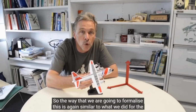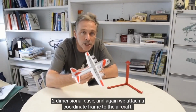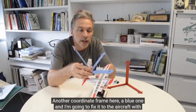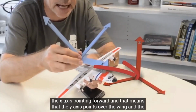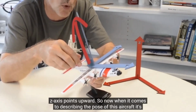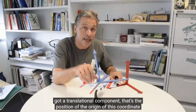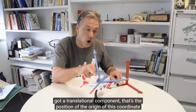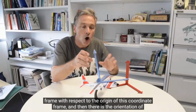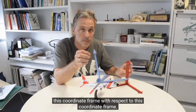So the way that we're going to formalize this is, again, similar to what we did for the 2-dimensional case, and we're going to attach a coordinate frame to the aircraft. Another coordinate frame here, a blue one, and I'm going to affix it to the aircraft with the x-axis pointing forward, and that means that the y-axis points over the wing and the z-axis points upwards. So now when it comes to describing the pose of this aircraft, it's got a translational component, that's the position of the origin of this coordinate frame with respect to the origin of this coordinate frame, and then there is the orientation of this coordinate frame with respect to this coordinate frame.